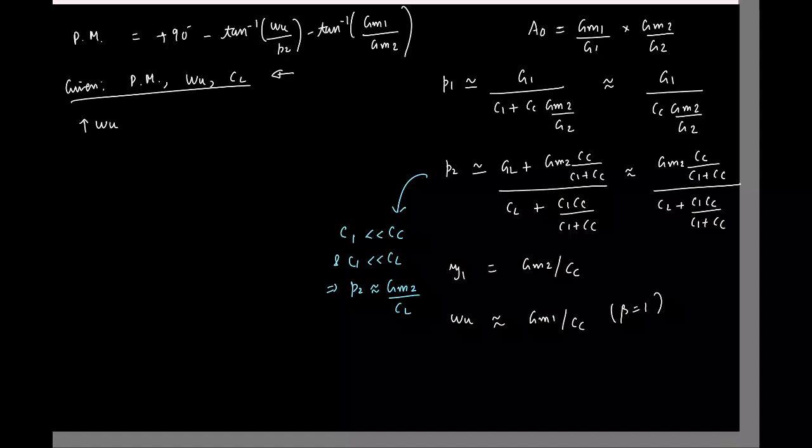That is, you want to make the closed loop bandwidth wider. So what can you change? Okay, so before that I want to increase omega u keeping the phase margin same. Okay, that's also important, same as before. Okay? Sorry, what should you do to increase omega u first?